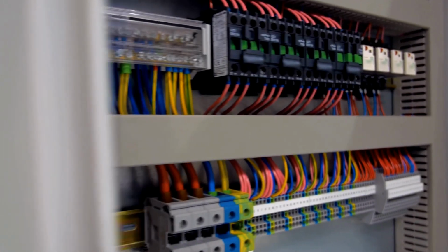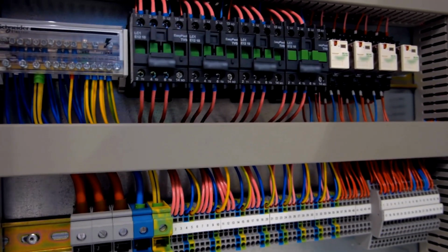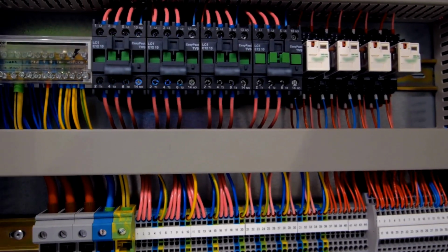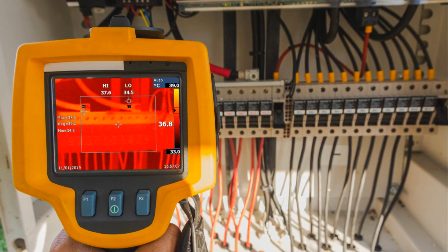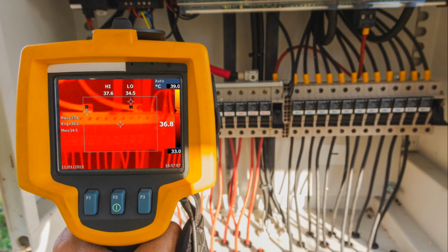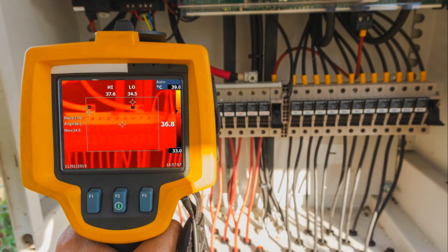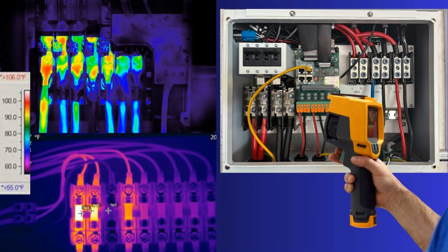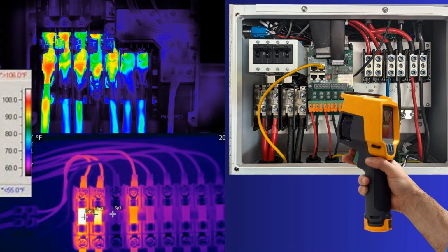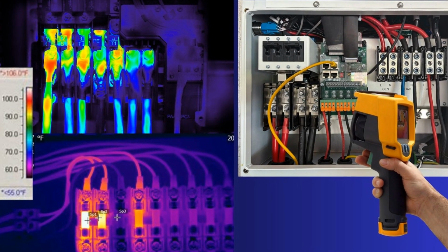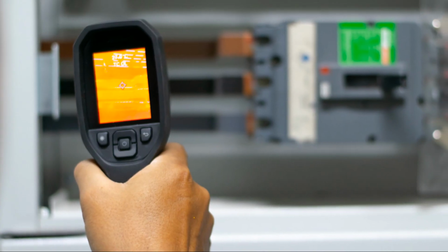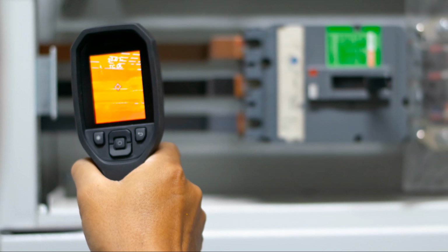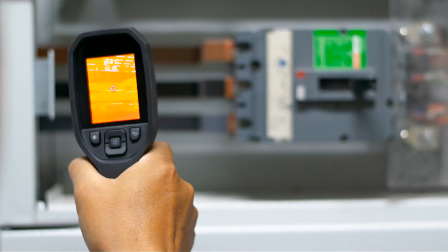Heat concentration around electrical connections often indicates loose connections, overloading or failing components, leading to excessive resistance and localized heating. These thermal patterns can also reveal high-resistance faults, damaged wiring carrying unintended current, and imbalanced loads, all of which may pose serious fire and safety risks. Detecting these issues early through thermal imaging allows for preventive maintenance, reducing the likelihood of failures, energy waste, and hazardous conditions.